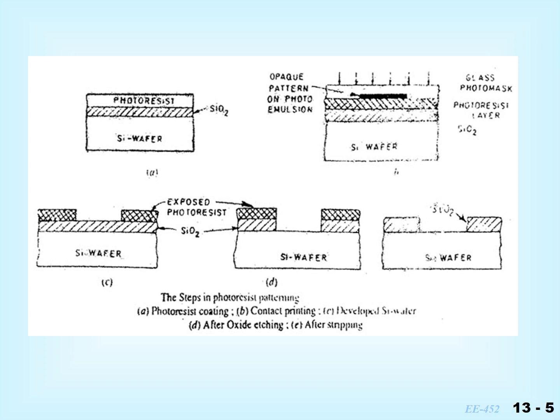After step B, when we come to step C and develop the photoresist, that means we put this wafer in some solution. The area which was not exposed, was not hardened, has not become stronger, will be removed.